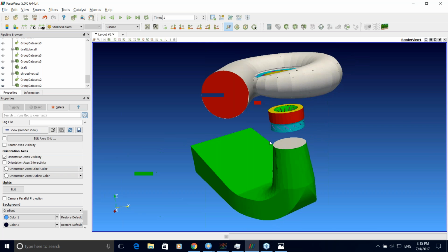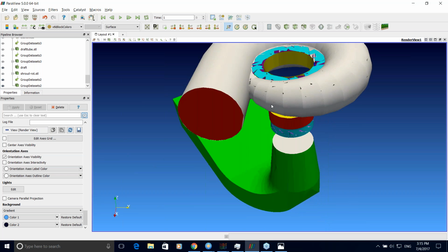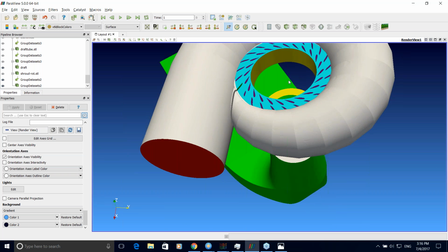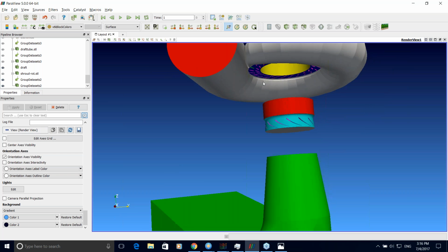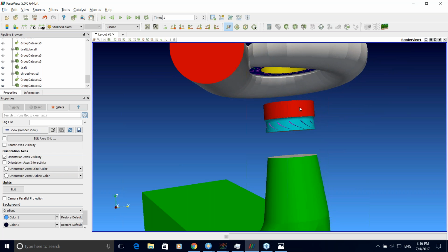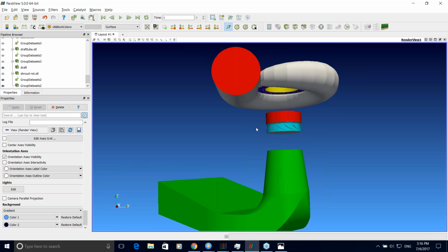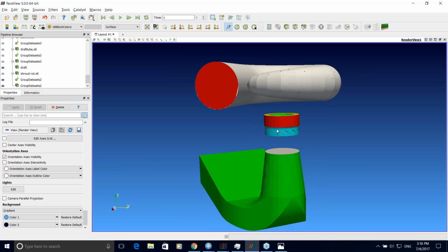So as you can see, these components are defined separately using these STL files, and there are interfaces between each component. So each component has to have each interface. Basically, each component has to be watertight, so it has to be a closed surface, and this is how the input geometry should look. And this holds for every type of machine, for compressors, turbines, fans, and so on.